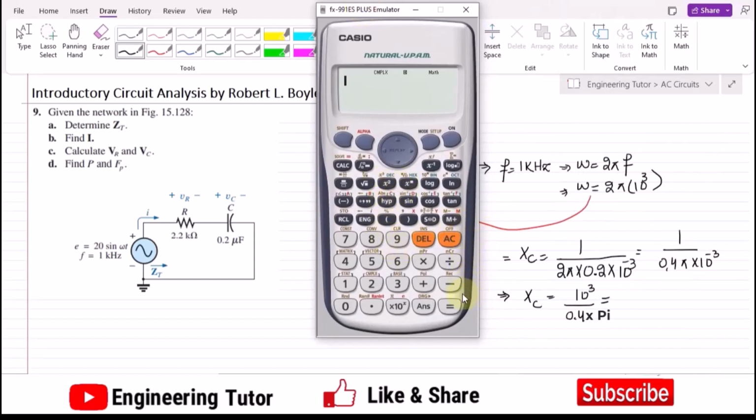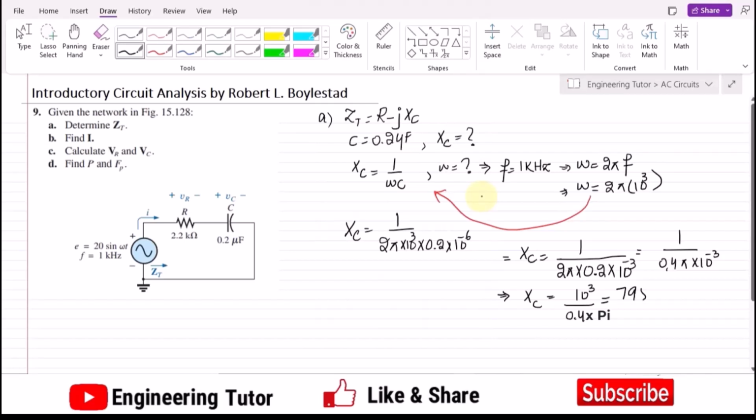That would be 1000 divided by 0.4 multiplied by pi. What I will get here is 795.77, which is 795.8 ohm. So that is the value of X_C.